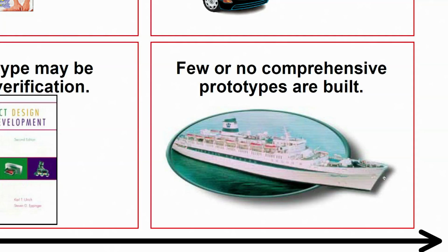And more than that, if you see the design of this hull, the total volume displacement and the various weights and various safety features, all these things. A full comprehensive prototype is not built, but small models are made. You would have seen in hydraulic labs, you will have this ship structure, probably scaled down 1:1000 or 1:10,000. It is kept in a water stream, and it shows how well it behaves. Even waves and all can be shaped, including we have here one chimney.